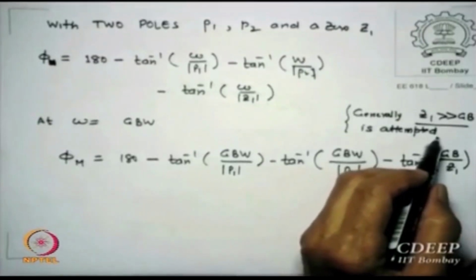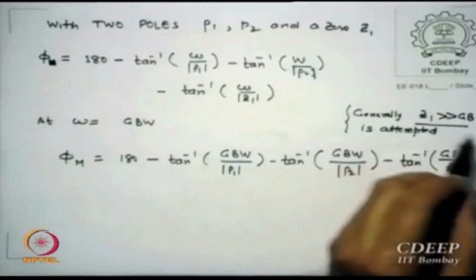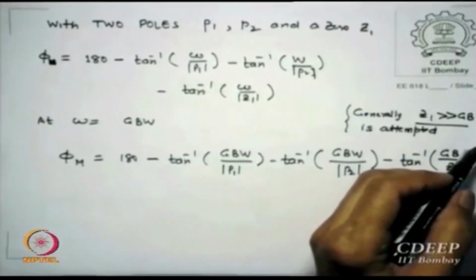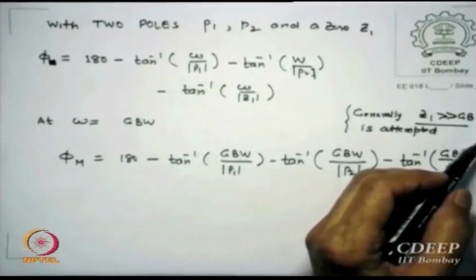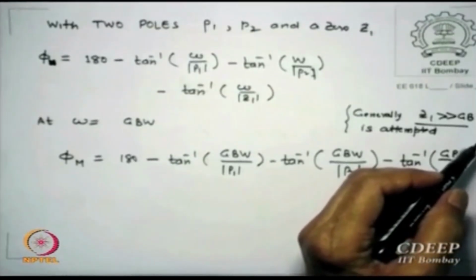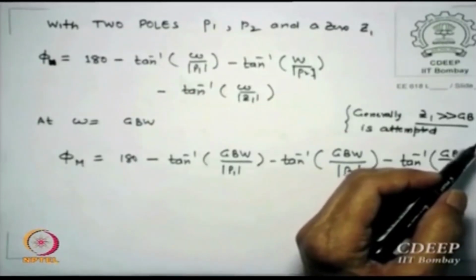Generally, because of the gm and Cc values, Z1 will be far away from GB. By the time the second pole has already gone to minus 80 dB or minus 100 dB, another plus 20 dB will make it minus 80 dB, but you are still well within your margin.